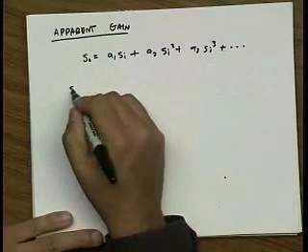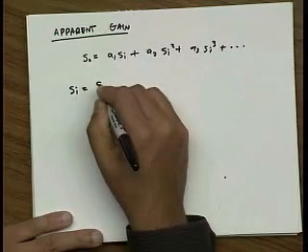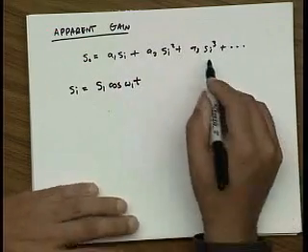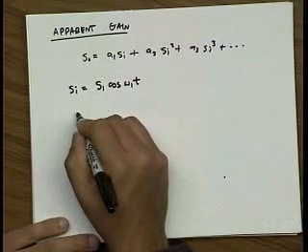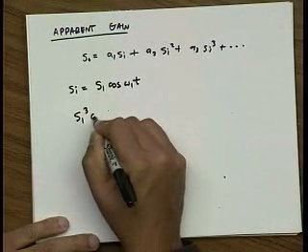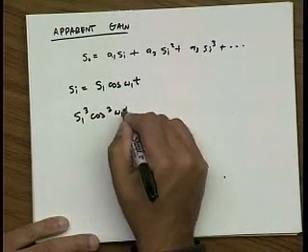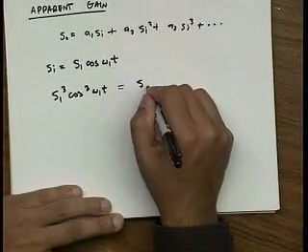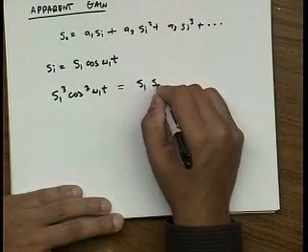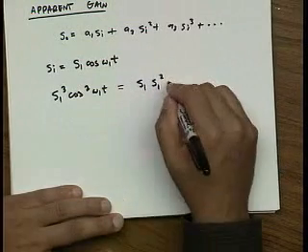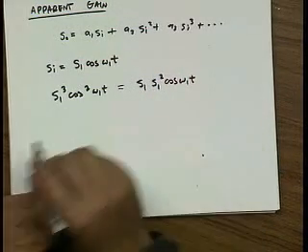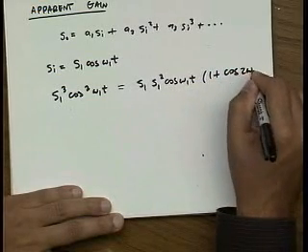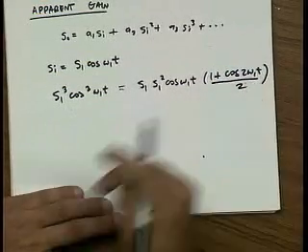So remember, if we put in an input amplitude, let's say S1 cosine omega 1t, and we look at the cubic term, S1 cubed cosine cubed omega 1t, I can never remember these, so I just do it from scratch. I can write this as S1 squared cosine omega 1t. Cosine squared I do remember, that's 1 plus cosine 2 omega 1t divided by 2.